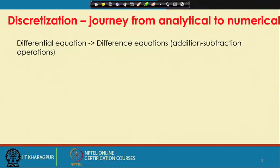It is a journey from analytical solution methods to a numerical method. We have a differential equation here, all rate equations, del T del t is equal to something, this is rate of change of temperature, or del 2 T del x square plus del 2 T del y square is equal to 0, which is the steady heat conduction equation, which is also about rate of heat flux, how rates of heat fluxes are related.